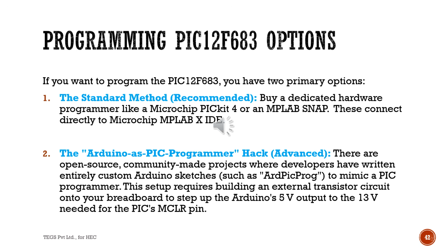Programming tool needed for PIC family microcontrollers. Programming PIC 12F683 options. If you want to program the PIC 12F683, here are two primary options. One, standard method, recommended. Buy a dedicated hardware programmer like Microchip PICkit 4 or MPLAB Snap. These connect directly to the Microchip MPLAB X IDE.